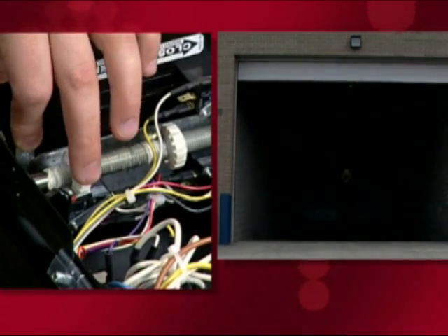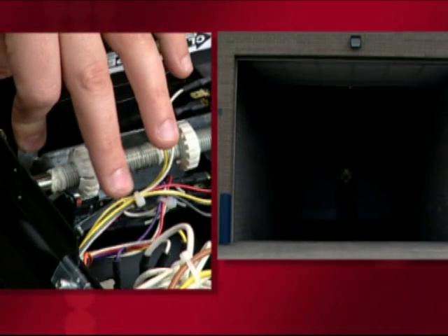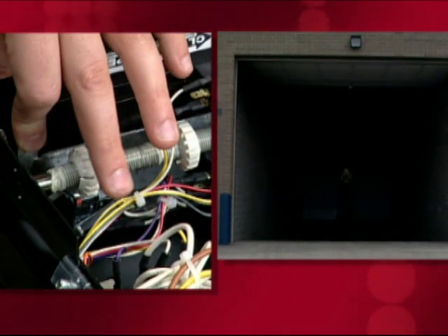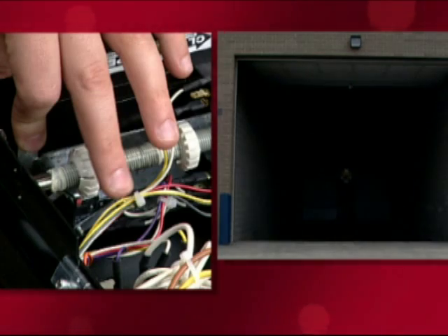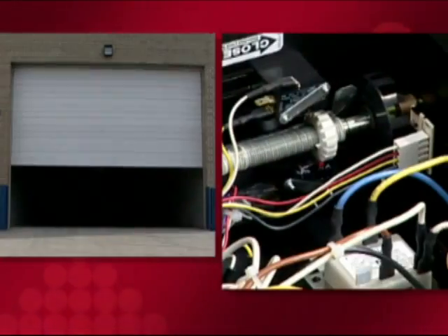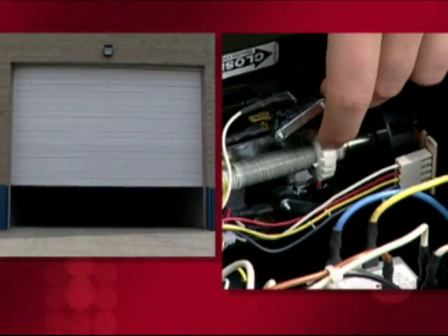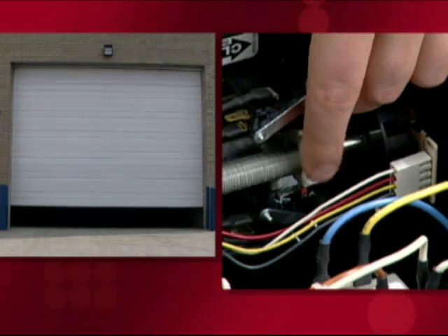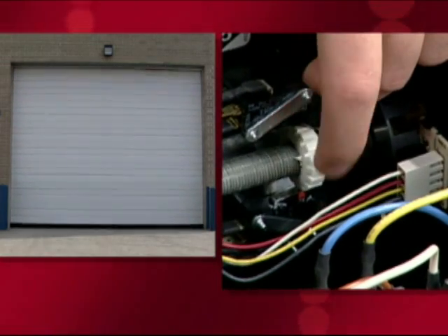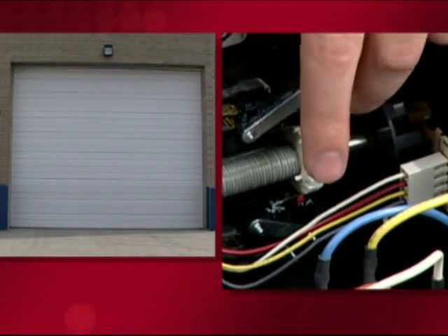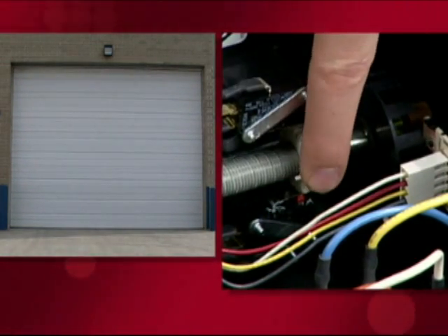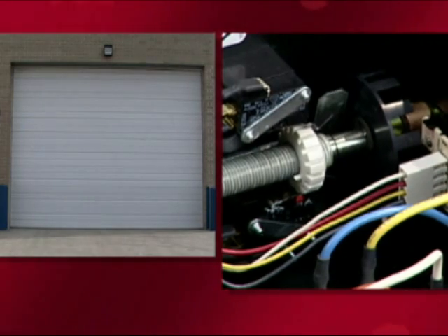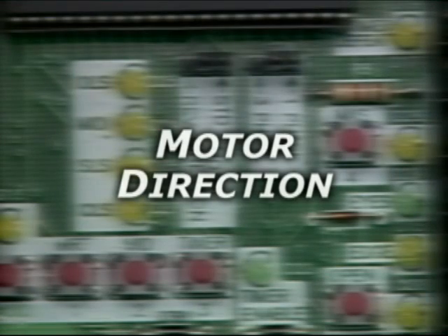Adjust the open limit nut so that the door will stop in the open position with the bottom of the door even with the top of the door opening. Adjust the close limit nut so that the limit switch is engaged when the door fully sits on the floor. After adjustment, release the retaining plate and check the limit nuts to make sure they are seated. Now, let us review how to change the motor direction on your operator.